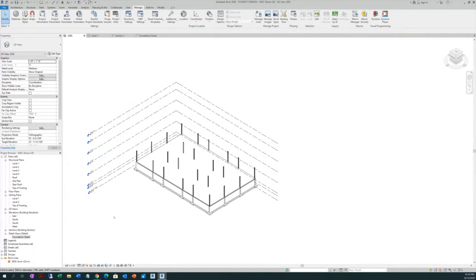You can have one legend and place it in all the title blocks. But a drafting view, you only do a drafting view one time, it is one place. You cannot have a drafting view on several sheets. A legend is different, okay?